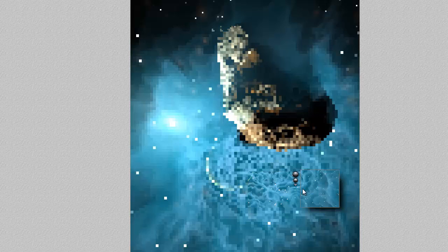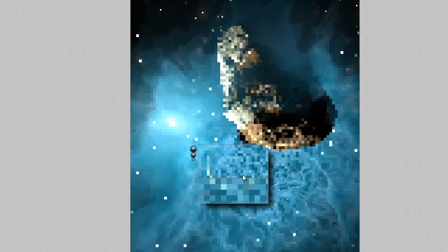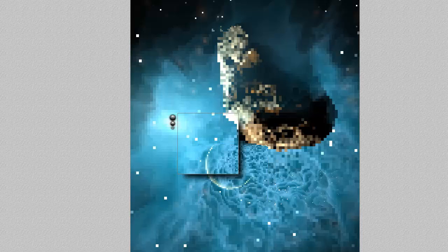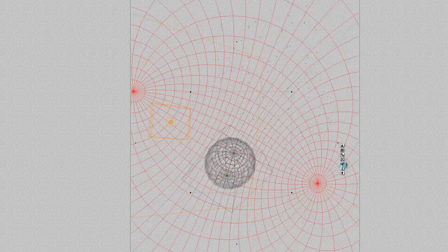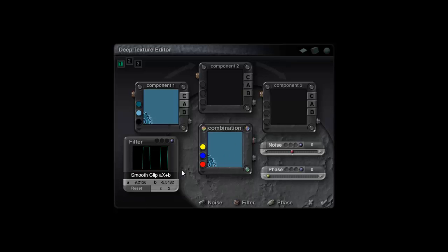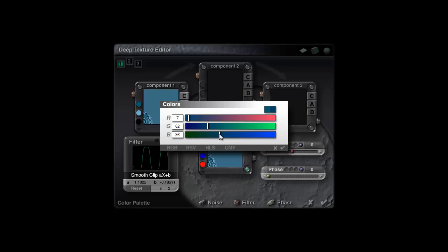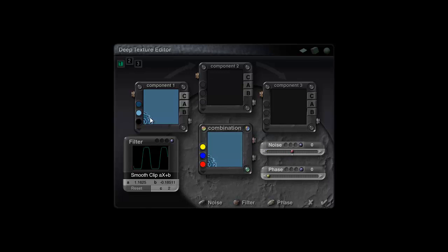So you can see now it's got these sort of hard looking edges, which might be a nice effect or might be a bit extreme, because you can see the layering. If you want to lose that layering, then you can reduce the effect of this clipping somewhat, not make it so extreme. If you just turn the colour off, you can see the effect on the alpha. And the other thing you could do was increase the contrast here. Another way of getting a more layered effect.